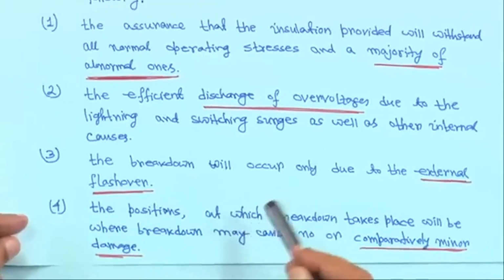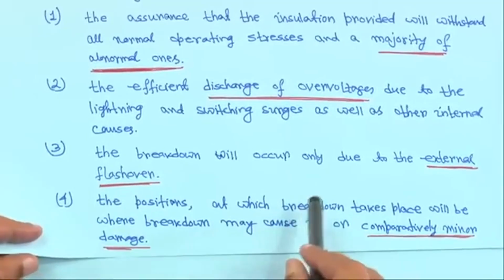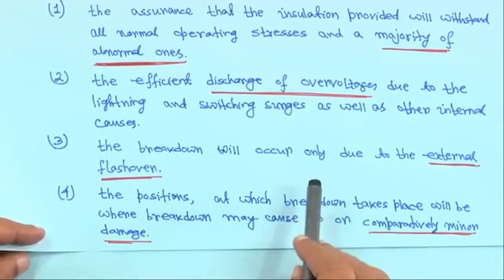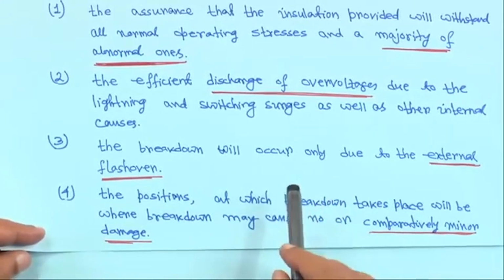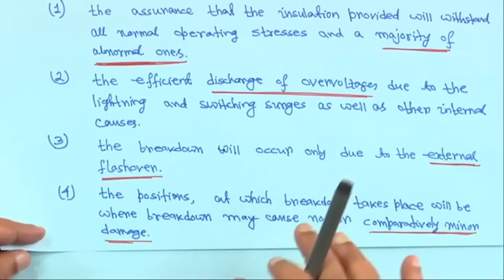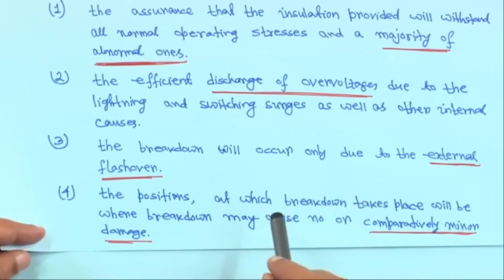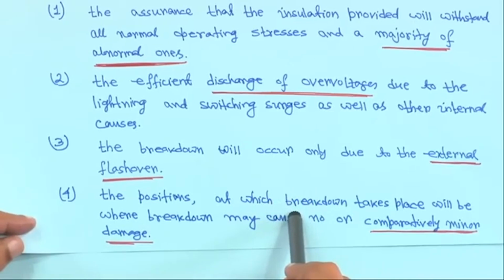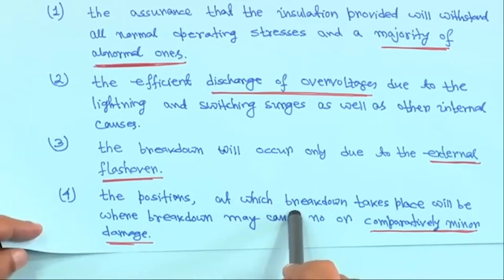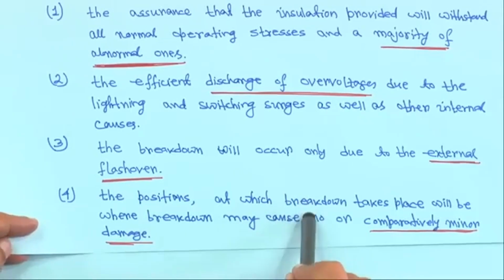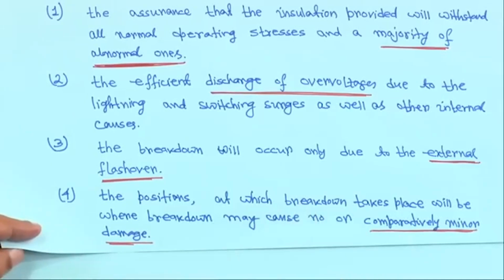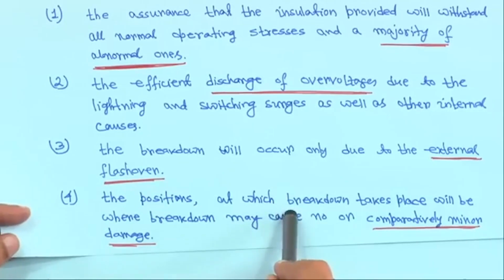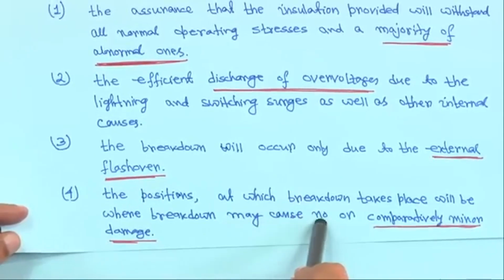When you test, you find that the testing is okay, but after testing, you do not know that out of the 200, one or two might have got damaged, because when you were testing it was okay. These are called hidden faults in that equipment. So, there is a possibility of that also.